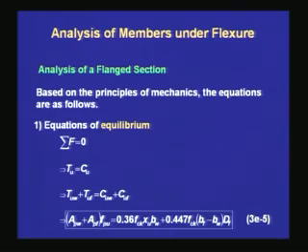Now, let us recollect what are the three principles of mechanics we use in our analysis of sections. The first one is equilibrium of forces. Here we have two equations, one for the longitudinal force and the second is for the moment, that the internal moment is equal to the externally applied load.